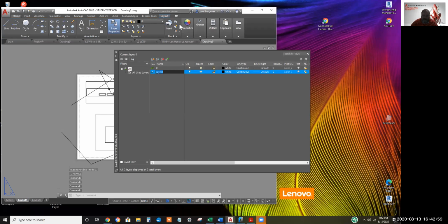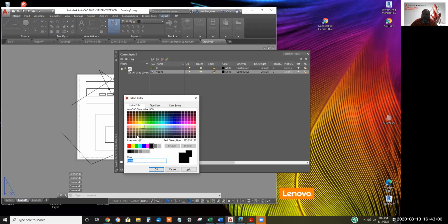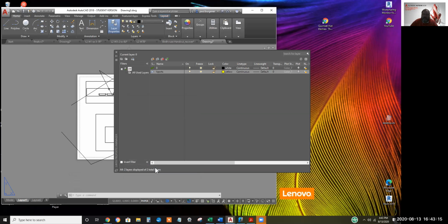So my advice is to create a layer called V-ports, assign it a very faint color like yellow. My handouts, I pick a darker shade so it does print out. Yellow is almost invisible. And rig it so it does not plot. It just occurred to me you could create your viewports or move them to the def point layer, but don't know anybody that does that.